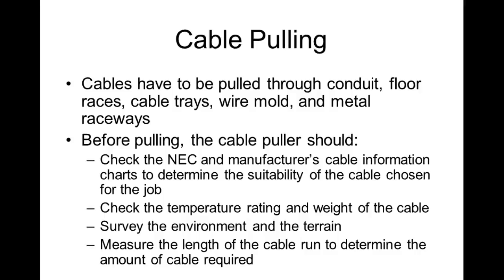Check the temperature and the weight of the cable, because we're going to start pulling. And when we pull something across something, we create friction, right? And of course, what determines the amount of friction is the two surfaces that are in contact with each other, and then the weight of what you're pulling. The problem is, if you pull these cables too hard, it's either going to break them or stretch them. And if you stretch them, you change the gauge of the wire. If you change the gauge of the wire, you change the ampacity of the wire, right? So there's a lot to pulling cables.